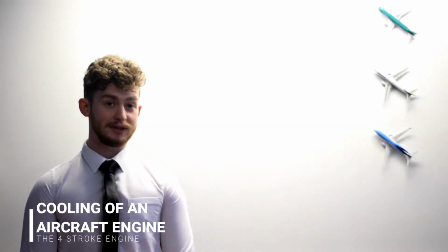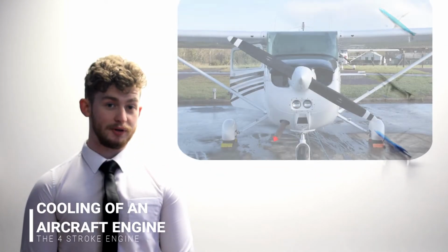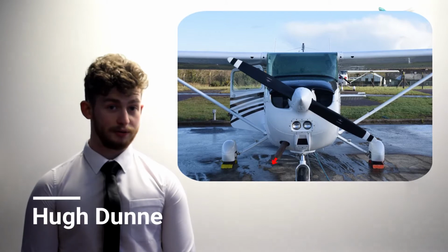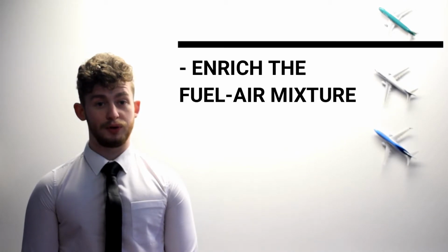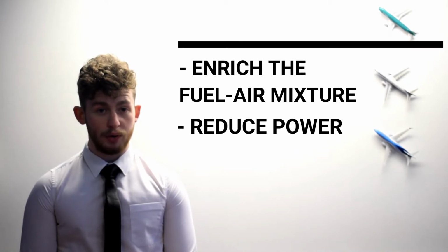Even though most of the intense heat produced by the burning fuel is expelled through the exhaust system, to prevent the engine from overheating, the remaining heat must be removed or dissipated. The oil system cools the interior of the engine, but there are numerous ways to cool the exterior of the engine: enrich the fuel-air mixture, reduce power, or even increase the airspeed.